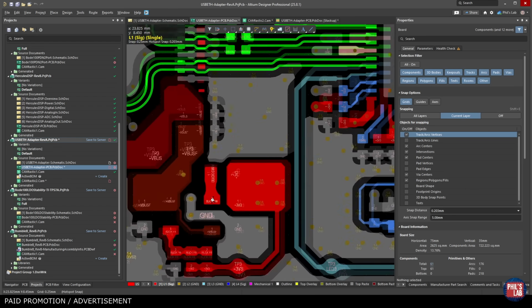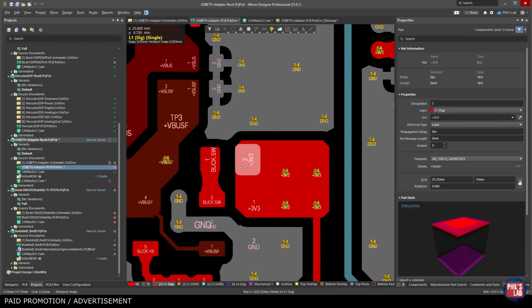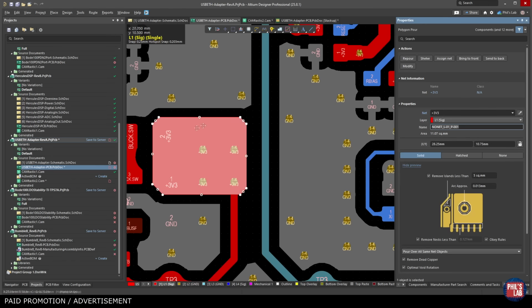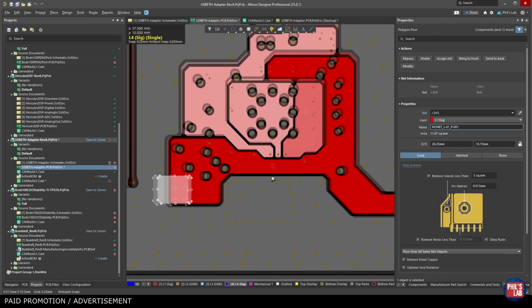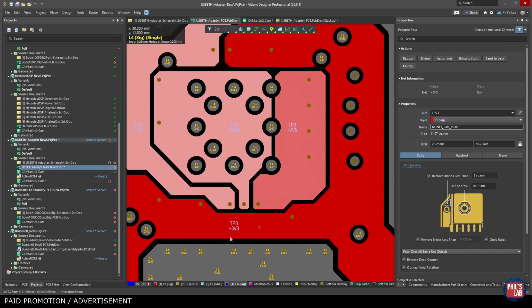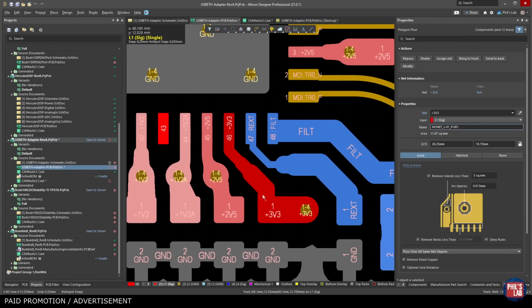Now with all of this set up, we've set pin 2 of our inductor as our 3.3 volt voltage generator. We have this small polygon planelet connected to 3.3 volts, and we have a couple of vias that go from layer 1 to layer 4 and feed this somewhat small polygon pour for 3.3 volts. We can go up through some vias, feed through a decoupling capacitor into the relevant pins of our physical layer. So that's what we want to simulate.